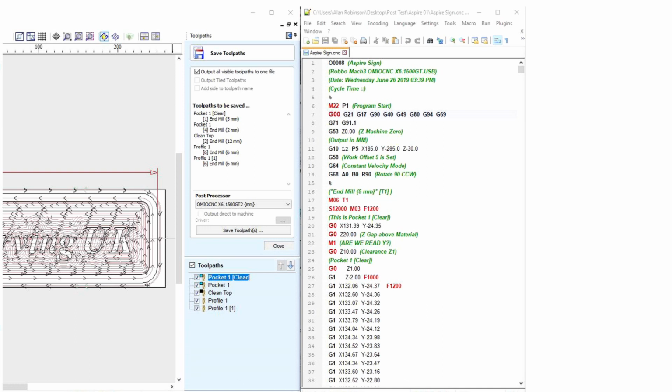G20 and G21 unit selection. Program G20 to use inches for length units. Program G21 to use millimeters. It is usually a good idea to program either G20 or G21 near the beginning of a program before any motion occurs, and not to use either one anywhere else in the program. It is the responsibility of the user to be sure all numbers are appropriate for use with the current length units. See also G70/G71, which are synonymous.